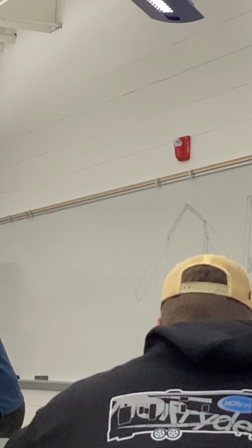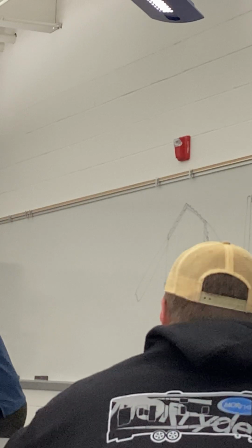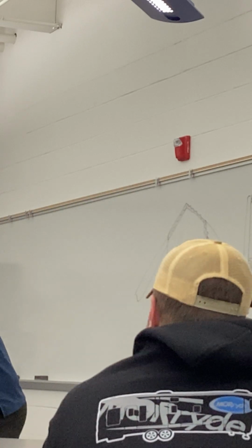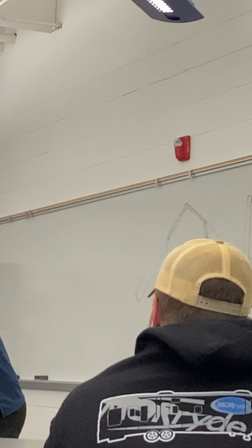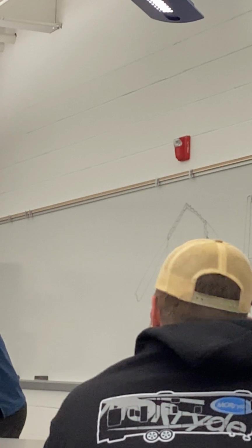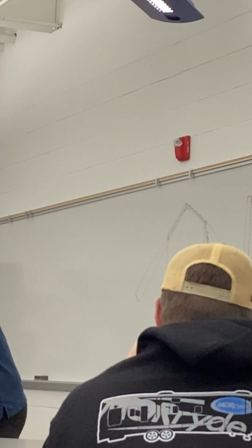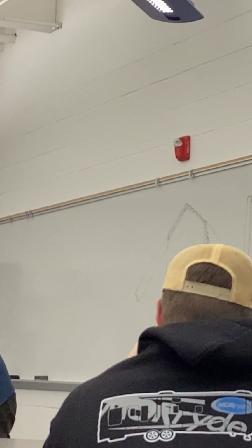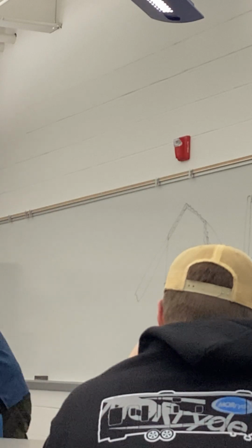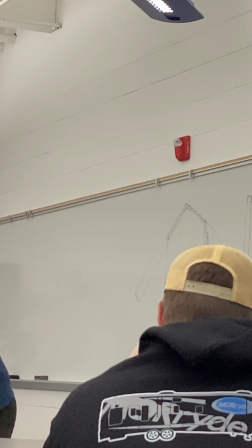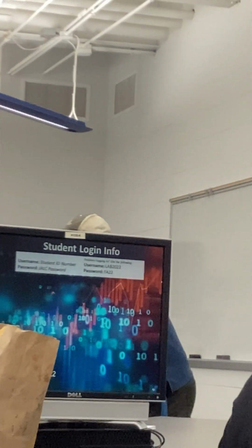What about attics? R24? It's ideal for the walls. Why wouldn't it be ideal for the attic? Okay, so where does heat go? Up, right? Heat doesn't go sideways very well. So we worry more about losing heat through the attic than through the walls. And we also trap exterior air in the attic through venting and everything else. So it's not really encapsulated, is it?